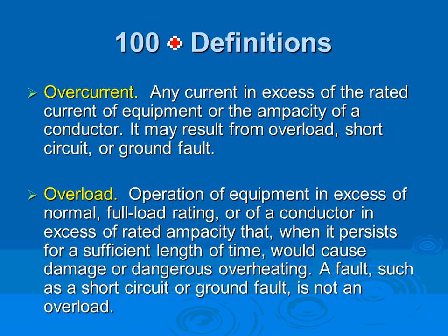What happened to my feeder? I have a panel here, 200 amp, fed from a 4,000 amp switchgear, right? Where's the overload protection for this panel? The fuse or the circuit breaker will provide it.